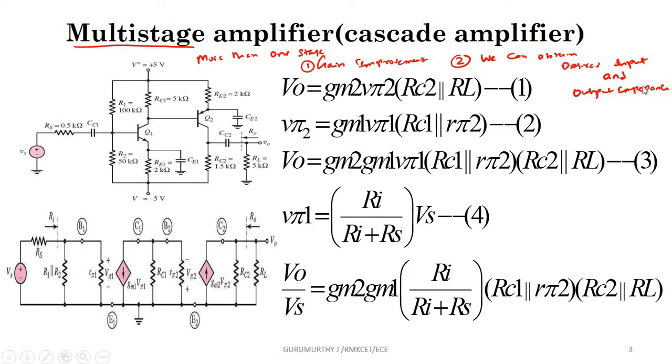case of feedback amplifiers, because if you use multiple stages then feedback could become positive, and the amplifier's purpose will not be served when it turns into positive feedback, because most amplifiers use negative feedback. When more stages are included, the negative feedback amplifier may be converted into positive feedback due to the feedback signal being in the same phase, right?